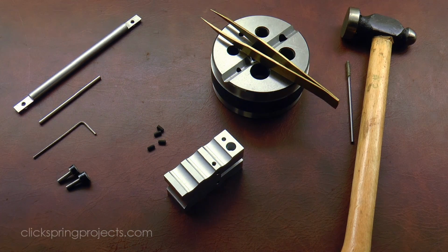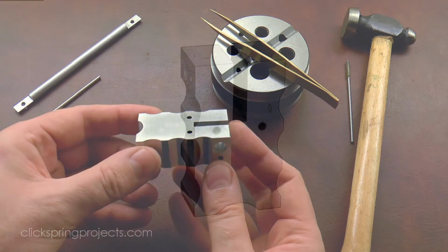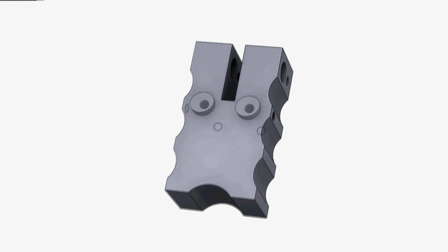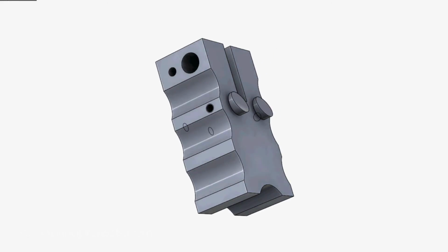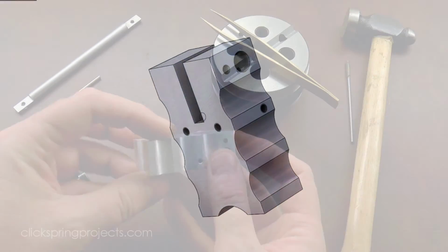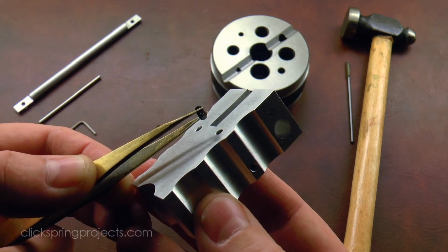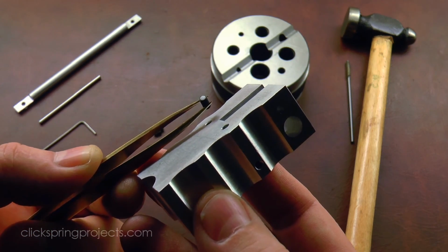Now you recall that I mentioned that this little cutter carrier serves multiple roles, and here's what I mean. The small holes behind the main slot are designed to carry the button cutters, both for the formation of their rake angle and also for sharpening. The design calls for a set of 4 grub screws to thread into the various holes to make all of this work.